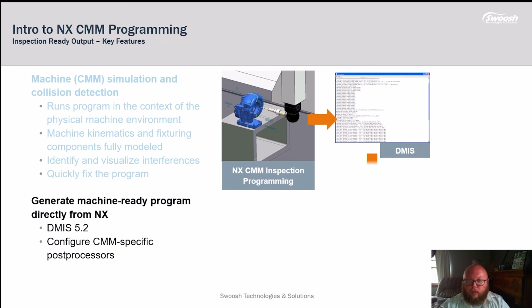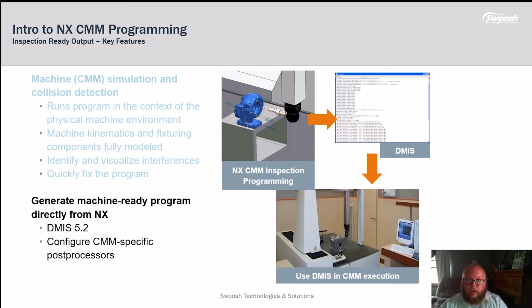And what we're going to output, typically the most common output, I should say, is DMIS, but we can support any post processors, or I'm sorry, any CMM machines. We can create post processors for any of them. There are many different types of CMMs out there, but largely DMIS based. But of course, there's other software like Calypso, and so on and so forth.